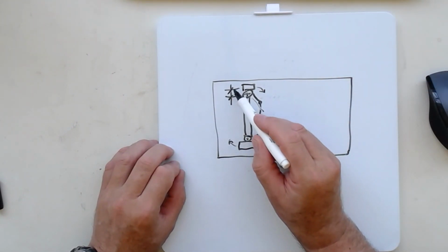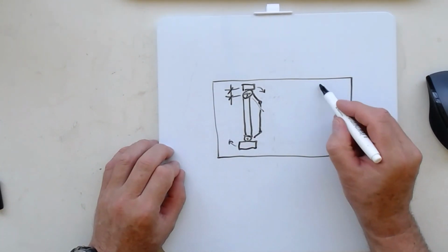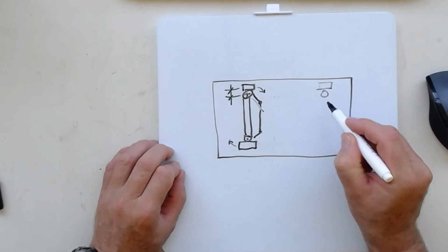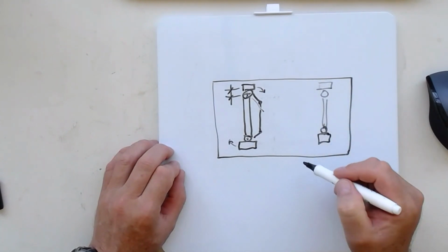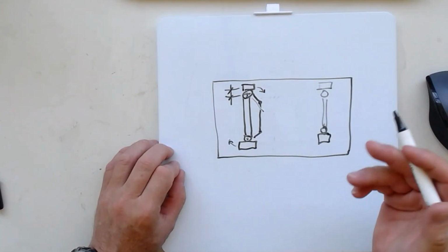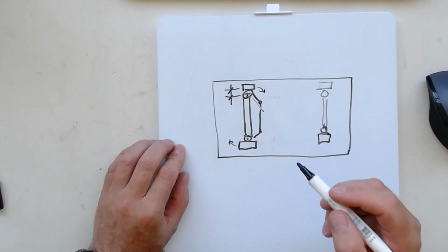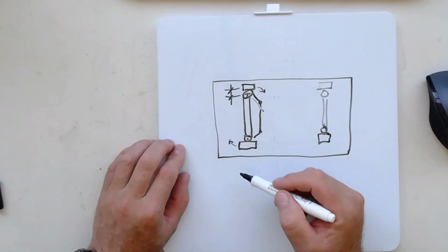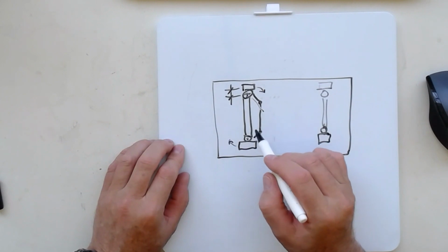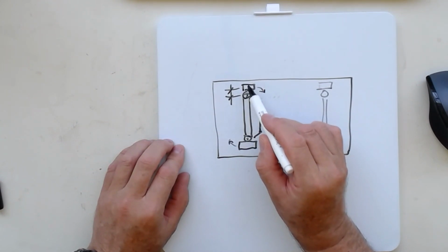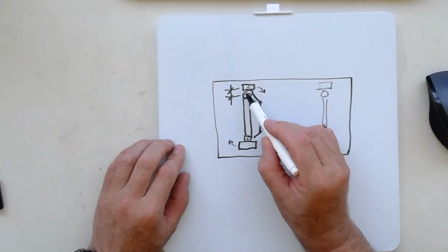The size of the torque is dependent upon that offset. Now what happens, particularly if you've got a four-wheel drive vehicle that might have park brakes on all axles, and will almost certainly have service brakes on all axles. If you've got your brakes fully on, you can't steer. And you are generating massive forces in your steering system by trying to, because this wheel will not roll. So how do I get it to turn around that pivot point?